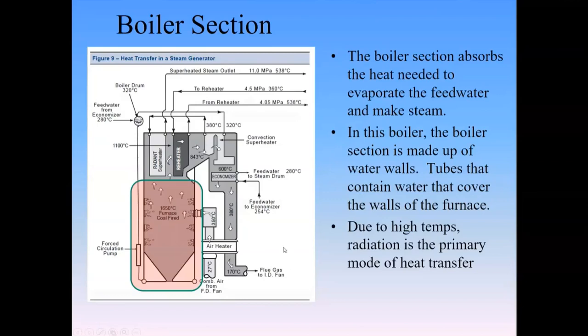Okay. And on the water and steam side, we have water that comes in, goes through an economizer, makes its way up around here, and I guess over to probably our boiler steam drum over here. And it moves itself in and through kind of in the whole furnace area, and then would make its way, oh no, sorry, the other way around. So from the economizer, probably through all the furnace walls and everything, up to the drum, and then would go through a superheater over here and a couple different pathways to come out as high temperature superheated steam.